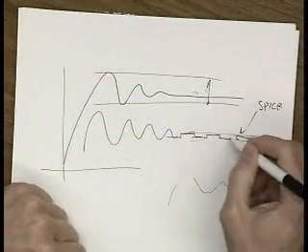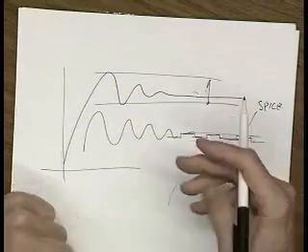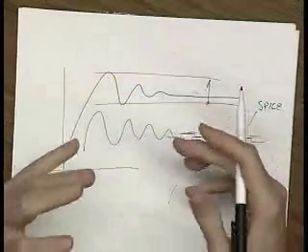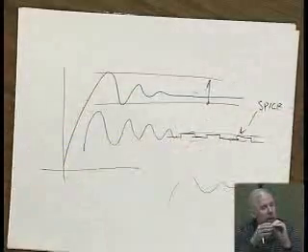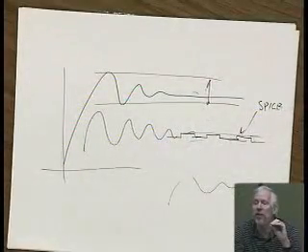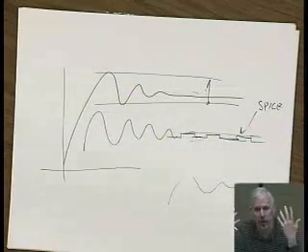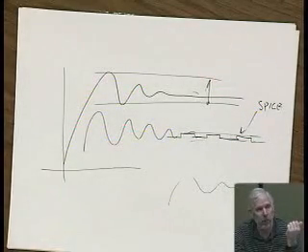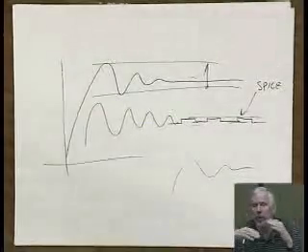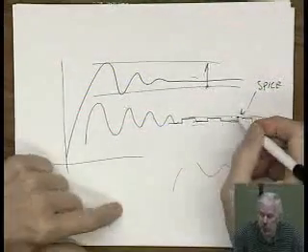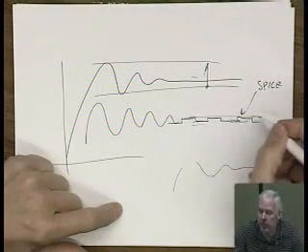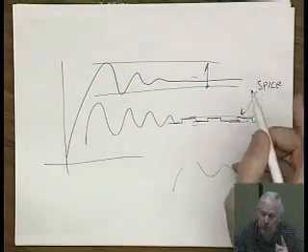to help you do that, because some of you are having some weirdness occur. For example, the static settling should not be a function of any capacitors. Static settling means after everything's come out to DC value, all the capacitors will be open circuit, so there's no effect from capacitance. Some of you were seeing the static settling change with the capacitor value. What was really happening was the accuracy of SPICE working up against its limits. Okay, so that's one point.